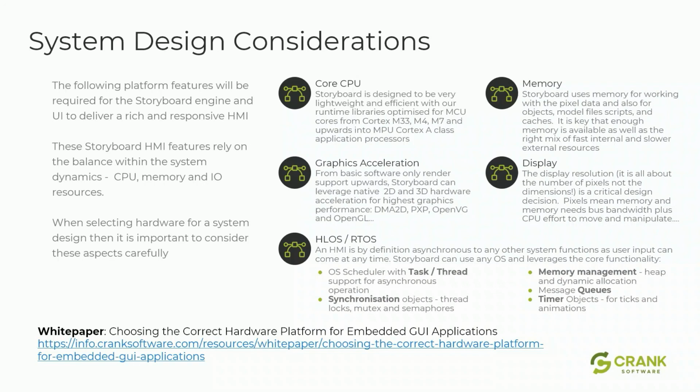Critically, memory management is a key thing again. We use heap and dynamic memory. This is for inflation buffers and all sorts of things. We're very good at reusing and recycling it, but it needs to be managed, so you can't just statically allocate it. And to communicate between the front end and back end state machines, you need queues, and we send events backwards and forwards using queues.